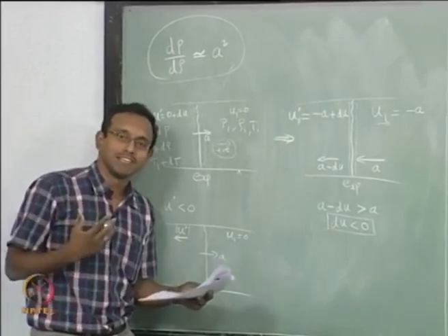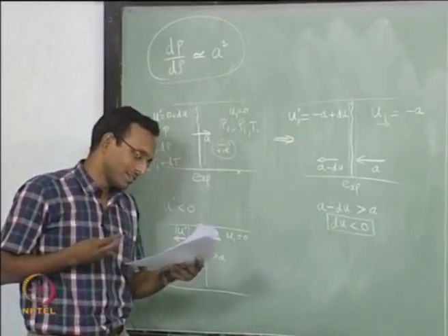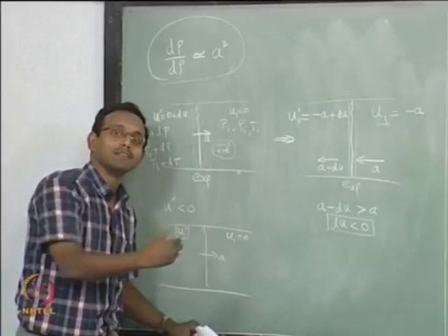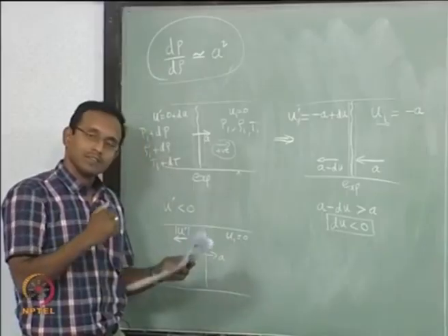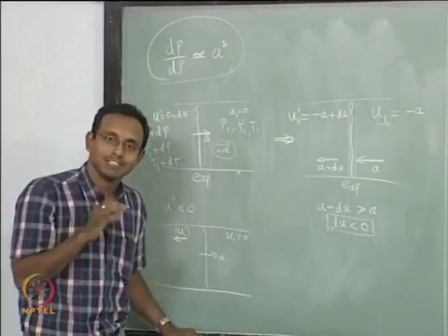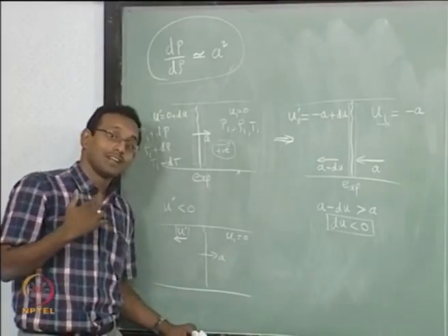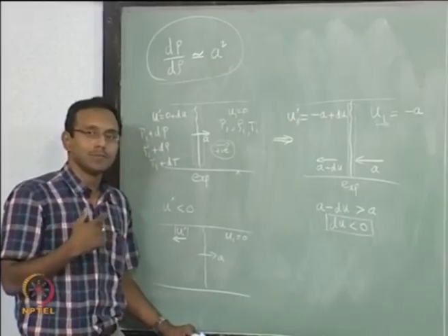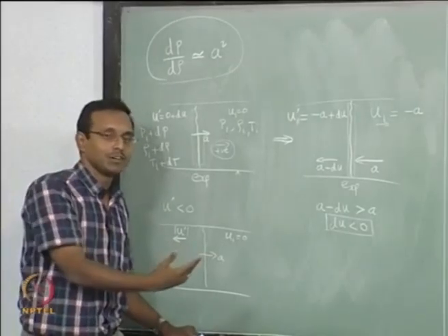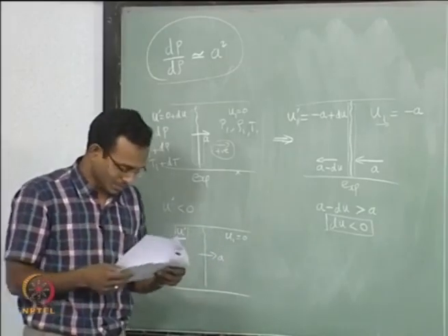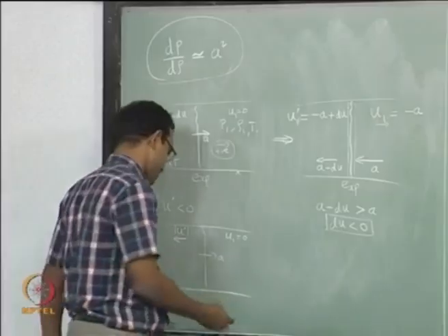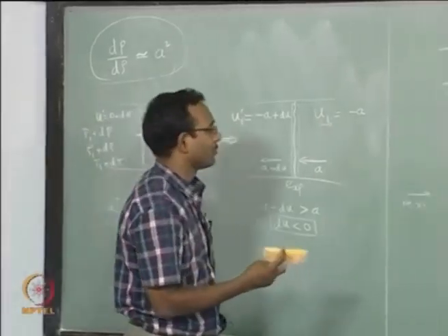Now I will just think of expansion waves as some person who is running, telling the fluid it is just now contacting, go to where I am coming from. That is the information it is telling. While in contrast, the shock is going to tell the opposite: come along with me. They are going to tell opposite information. If you think about this, it becomes easier later when the problem becomes more complex.